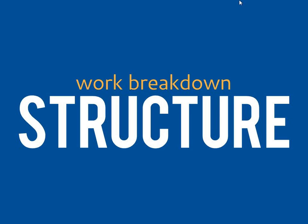And so the next step is to define that work breakdown structure. We want this to be as detailed as possible and break it down to a specific activity level so that we can apply labor, equipment, and material and have an accurate assumption for each task. Our goal is to be able to pull up any activity during a bid review and justify our assumptions by being able to point to the crew and the productivity that we've defined.